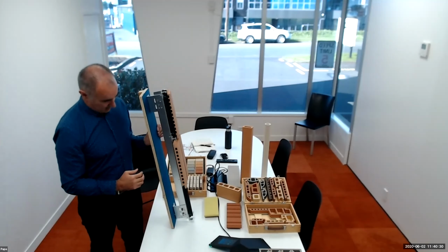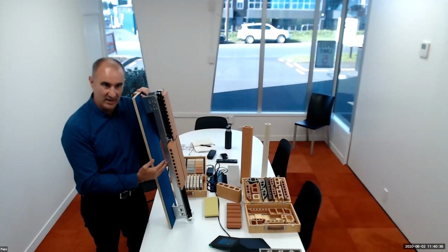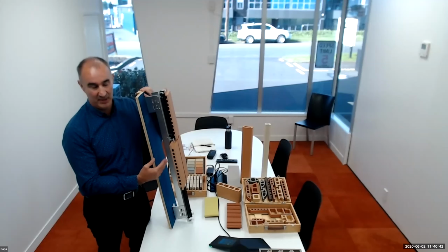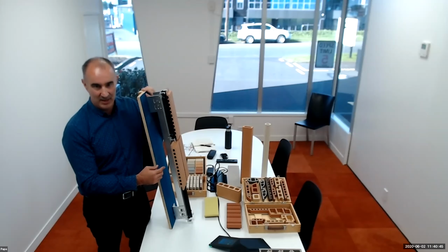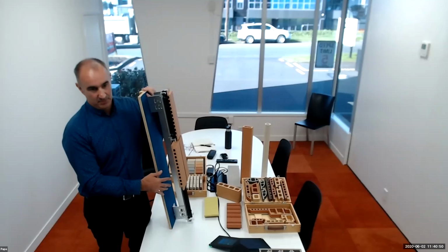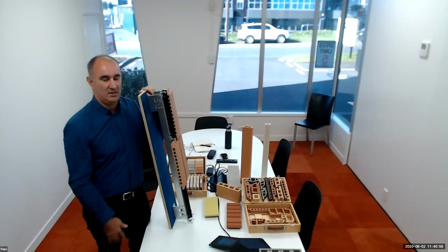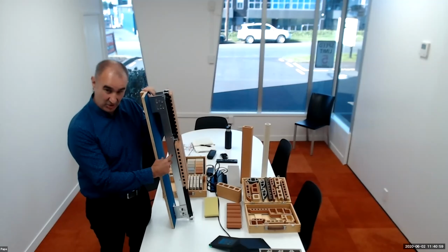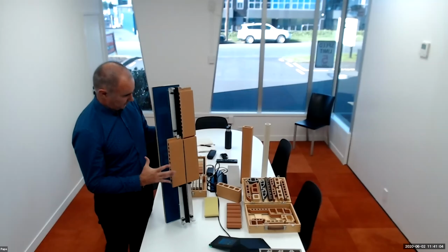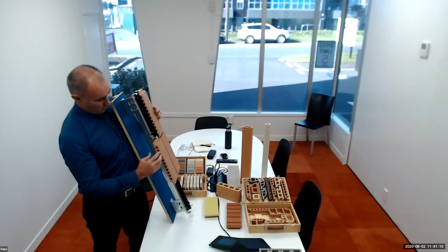Why I say you'd probably use this more overseas is you've got this space in here you can utilize for, say, insulation. You can wrap the building. There are plenty of rain screen insulation products out there, or use it for your services, cabling, plumbing. Your downpipes and everything can run in behind here. So if you don't want to see that aesthetically on the outside of the building, use this space. We can do that. And then, as I said, we wrap it up, gets it all tight.